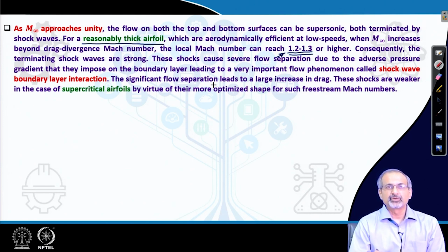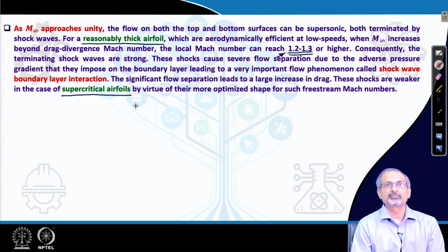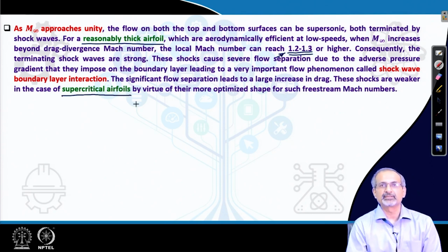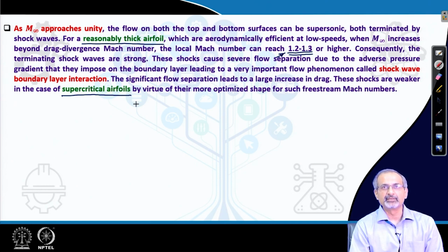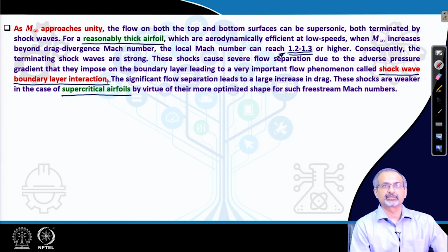And this is where comes the utility of supercritical airfoils, which can suppress these flow separations and associated complexities with shock formation, and therefore, the drag can be dramatically reduced. If you have strong shock formation, there is also an additional complication of what is called shock wave boundary layer interaction. So,